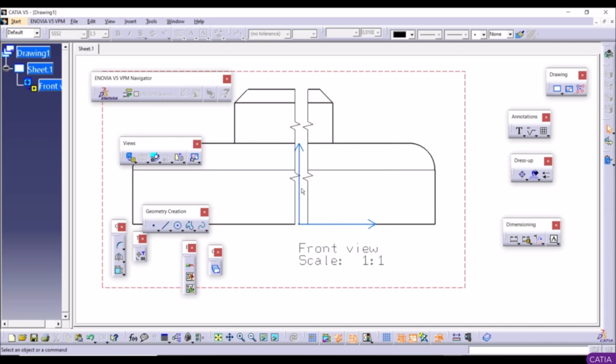So when you have a huge view, you can break this view to fit on the paper. And everything that is between those two breaking lines is continuation here of this view on the left and this view, those lines, as you can see here on the right.